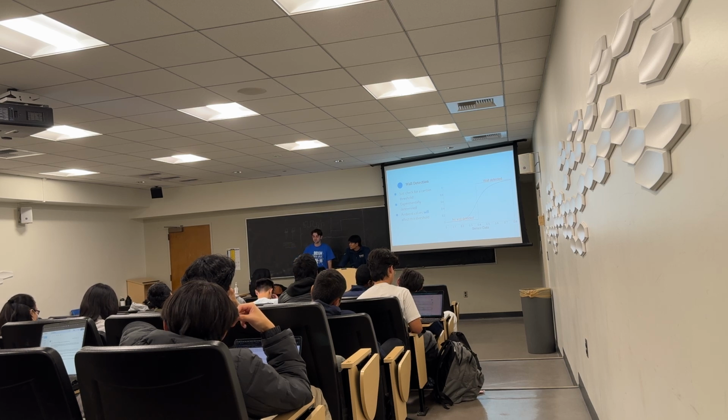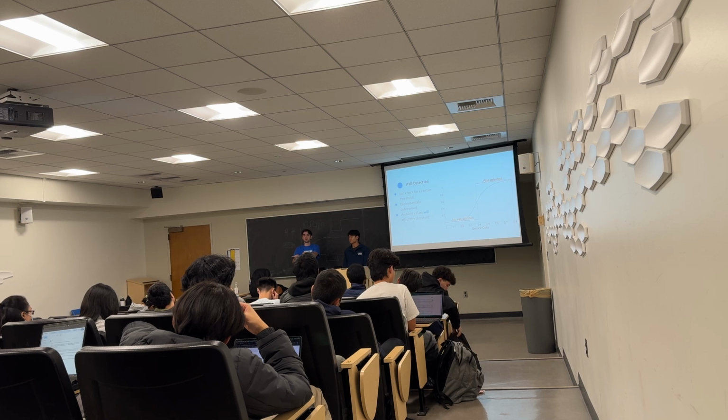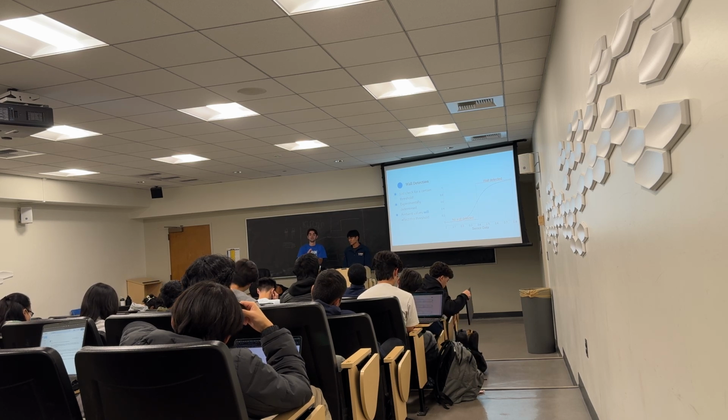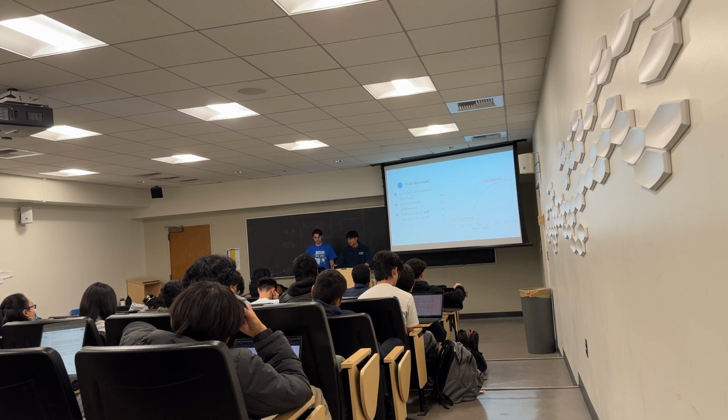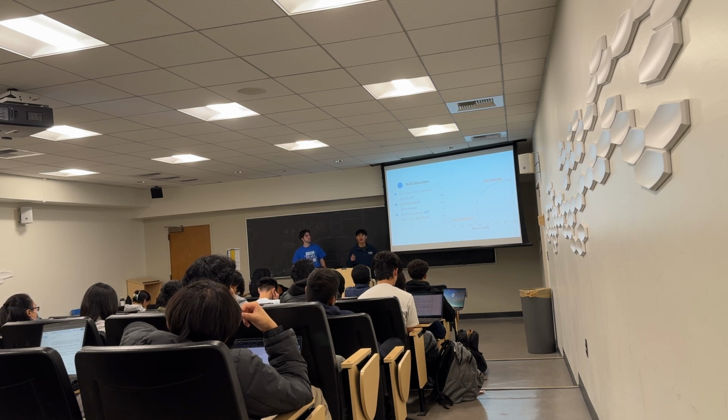Remember earlier I said you place it 1 inch from the wall, and then you read the values. Then you say, okay, that means a wall is to the left, and anything less than this is not a wall, so you can move there. Basically, you're setting a wall threshold where you want your mouse to say, hey, there's a wall, I want to turn. It's basically saying, when do you want to turn?